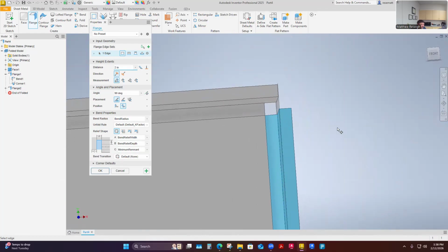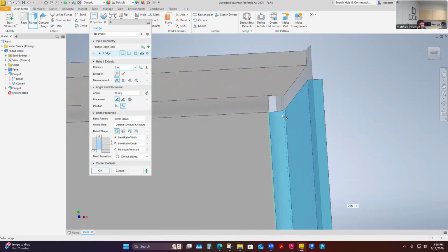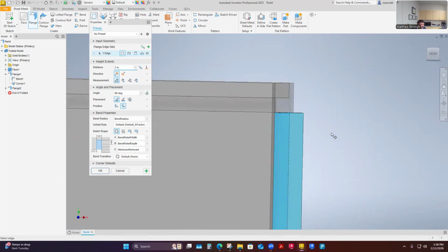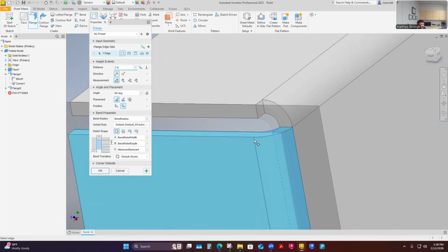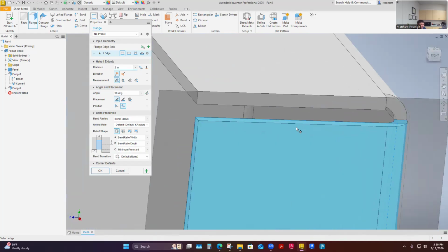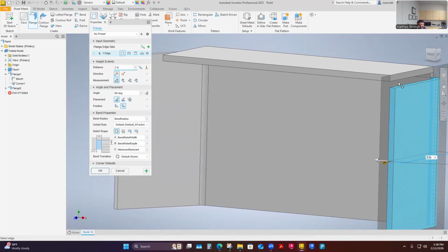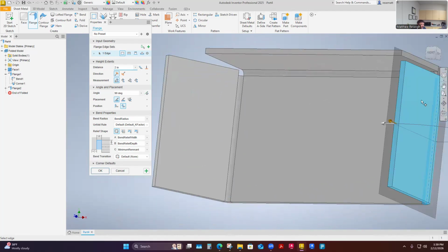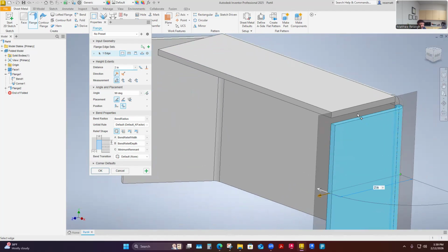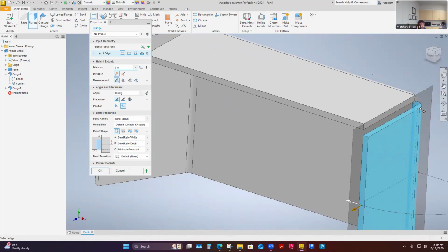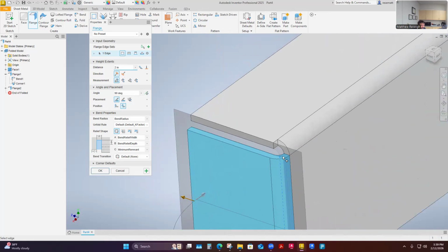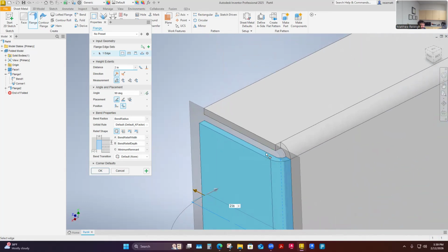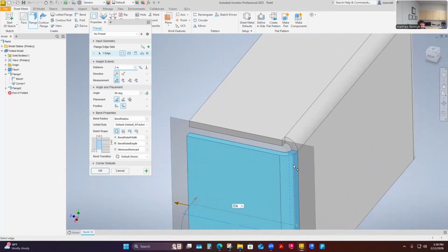I think if we get rid of some of our gap size dimensions or put the gap size to 0, I can drive these two parts so they lay perfectly aligned and I'm not creating quite a large gap in materials here. Welders don't love that. There are gaps for a reason, yes, but gapped if I don't need to, no. They would prefer, if this is going to be a welded joint, that I drive this edge together with this other edge and create a really nice, what I call an outside corner joint, right?